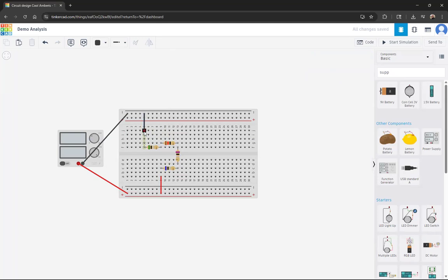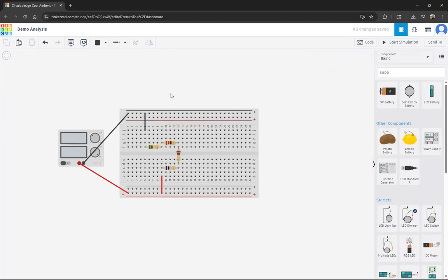I can always click the end of this wire. I could add jumpers in that same hole. I don't recommend in Tinkercad specifically, I do not recommend, even though I can click this red and drop, say, another wire. I do not recommend doing that because you can't do that in a real breadboard. We can't double up on holes. So I recommend setting this up exactly the way your physical breadboard will be set up. Keeps things nice and clean that way.